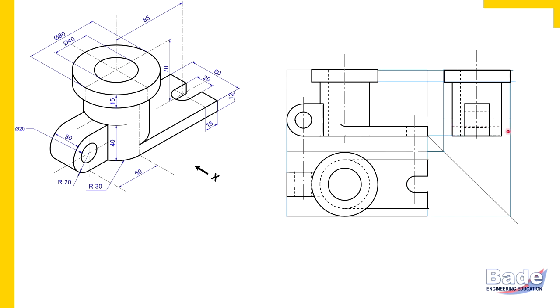Where is this base plate in the side view? If I ask you, you should show me the complete rectangle. Check here, it is attached to the cylinder from the right side, and the side view is the left side view. So from the left side this plate is hidden. So there is a dotted rectangle here. Watch here, this is that rectangle. But its three edges coincide with the earlier drawn continuous edges. Okay, you never draw hidden lines at a boundary, remember.